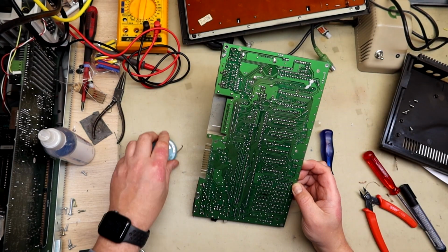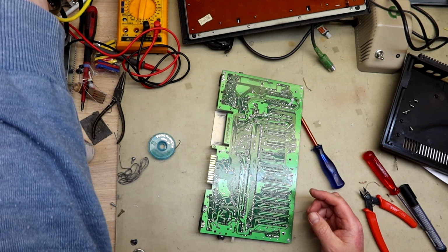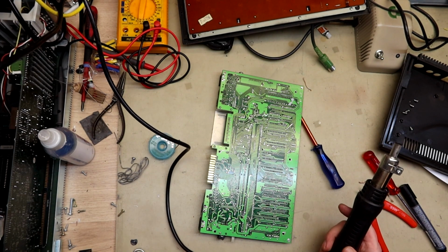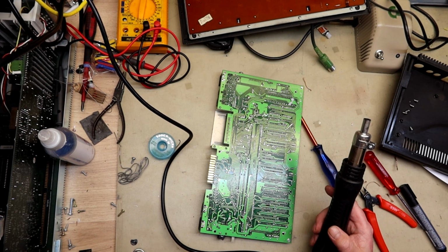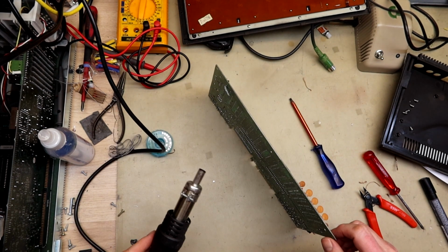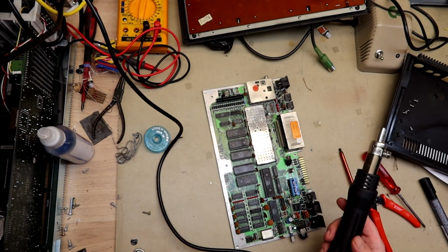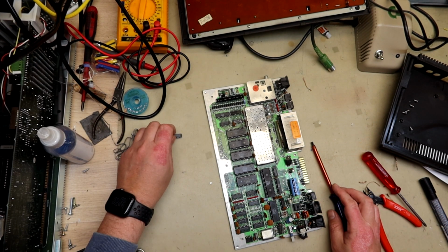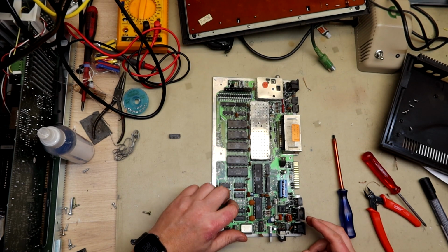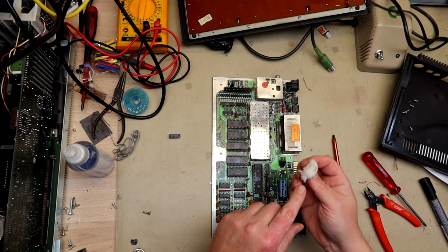And after you have done a manual inspection and seen that all the holes are open, even then it's wise to use a hot air soldering iron or a hot air gun with a thin nozzle to heat up the back of the PCB when you pull out the chip, to avoid applying any mechanical force on the solder pads. And this time all the preparations and hard work paid off. The chip easily came loose without persuasion. So now I just clean away the excess rosin with isopropanol.